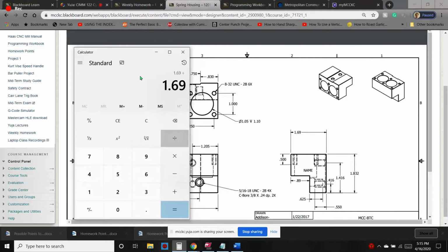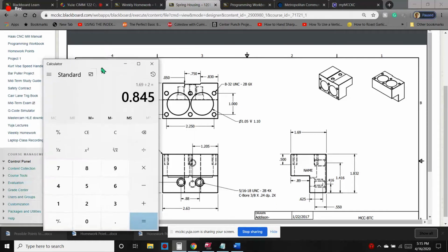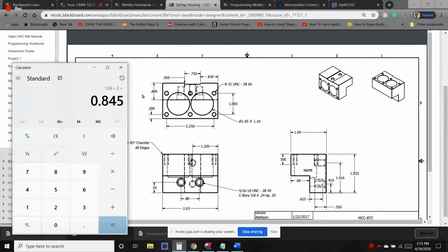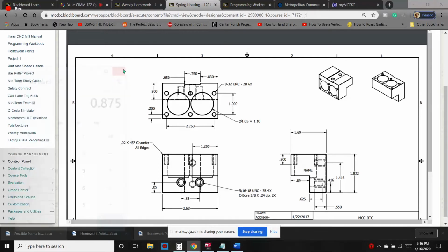The material is still 1.750 before we start cutting on it. So while that's not wrong, if you wanted your cutter right dead center in the middle of the part, it would be Y minus 875. 1.750 divided by 2, yeah, 875.